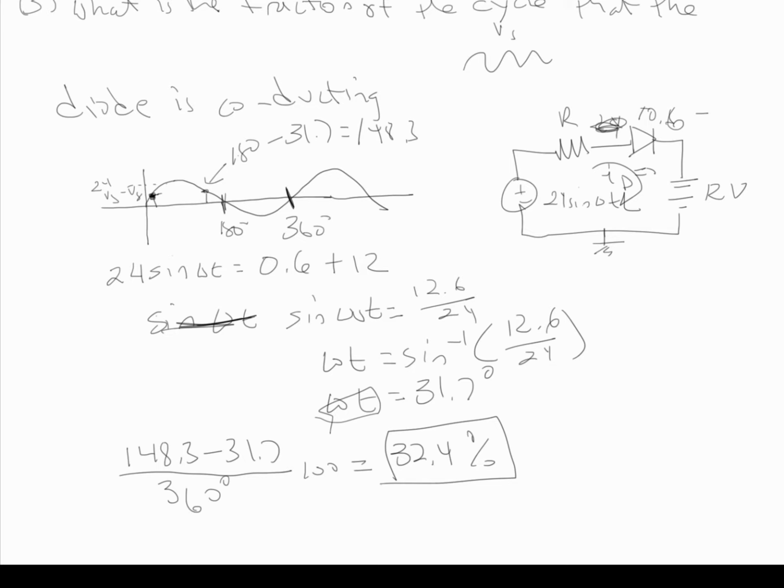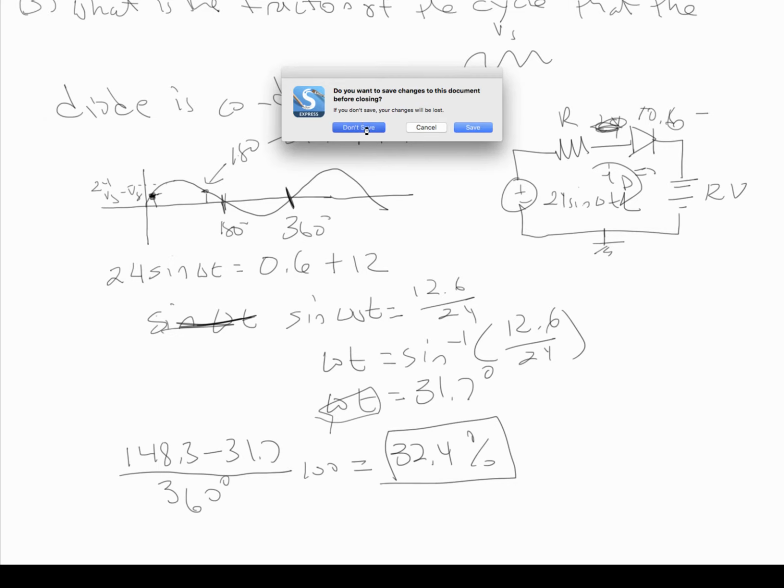Now, the next part, they talk about full wave rectification. So that's 2.1.2, full wave rectification. So half wave is, we used one diode and we got this half of the wave rectified, and then we kind of threw away everything that was below here. This was all thrown away. And so with full wave, we want to get an output that looks like this.